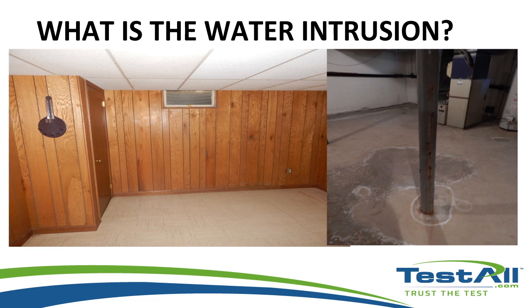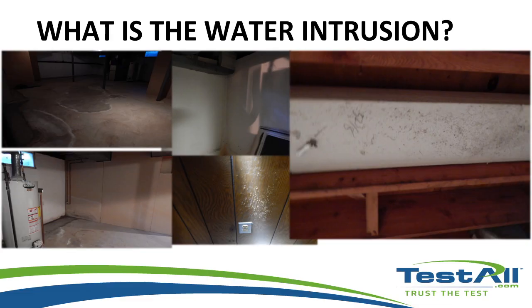And when you look at the base of this column, you will see efflorescence around the bottom of it, and you can see both water stains and efflorescence on the floor around that column. When we look at the next photograph, we'll see pockets of moisture stains on the floor. No actual water stains to any of the area items such as walls and floors in this area. But we move further to the next photo and we see a wall with sheetrock that's got moisture stains on it, probably from wicking up, mold on it.